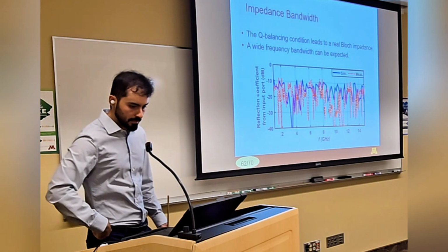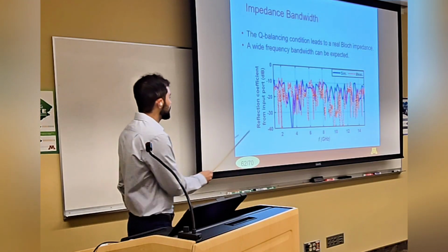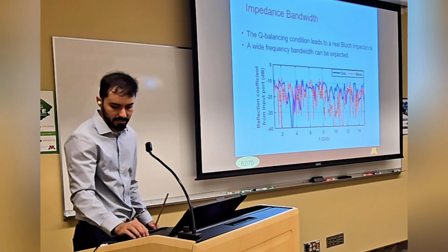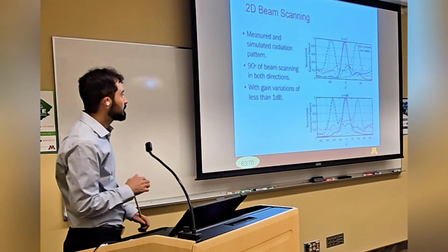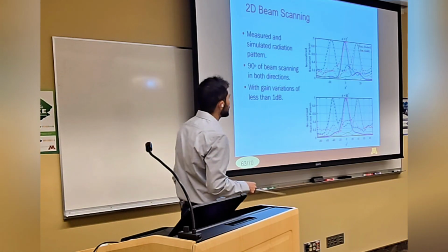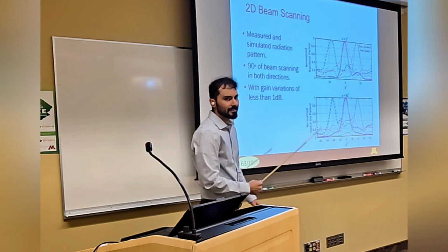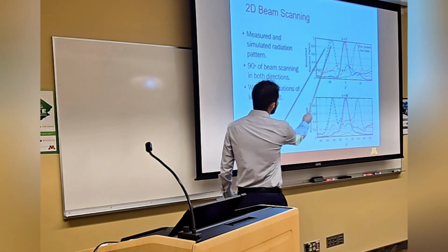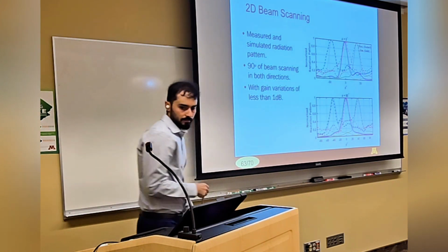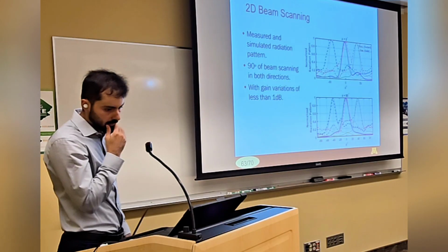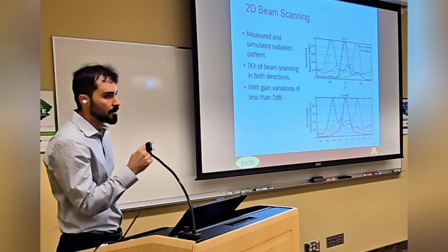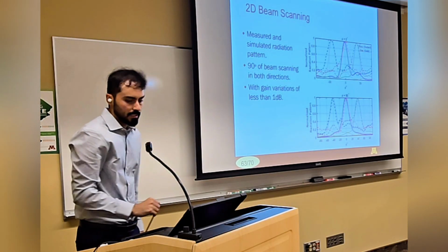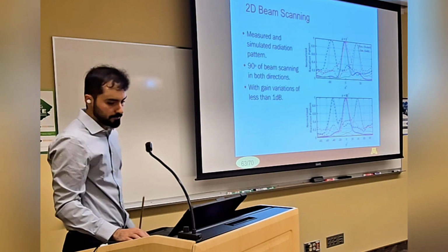This figure illustrates the comparison of reflection coefficients from the input ports that show the antenna is well matched in both frequency bandwidths around the center frequency, with the capability of a multi-port periodic antenna. This is the normalized value for the radiation pattern in both directions, E plane and H plane. It's obvious that the antenna can provide around 90-degree beam scan from backward to forward in both directions.